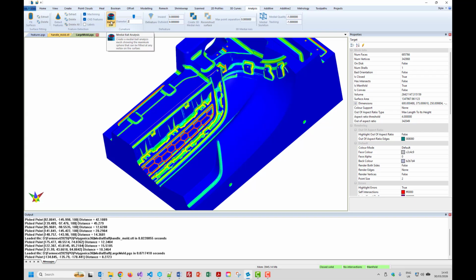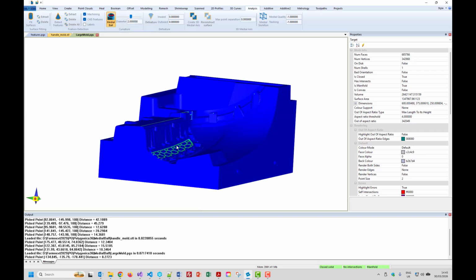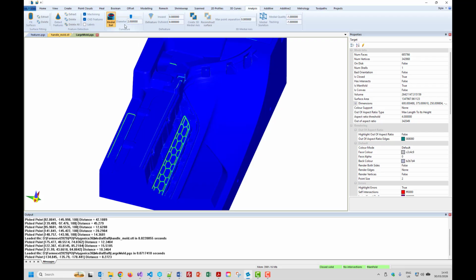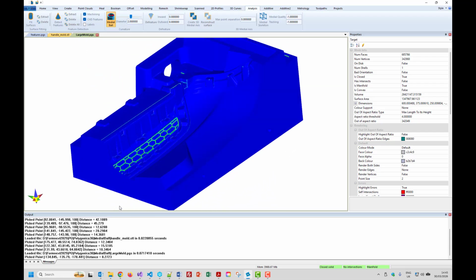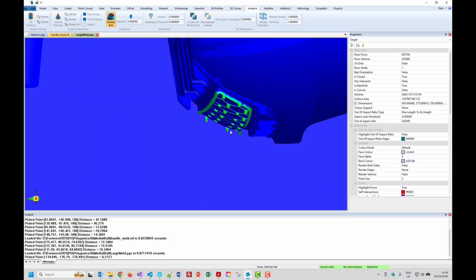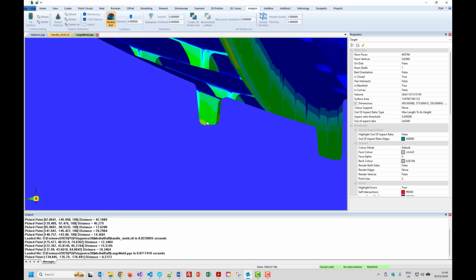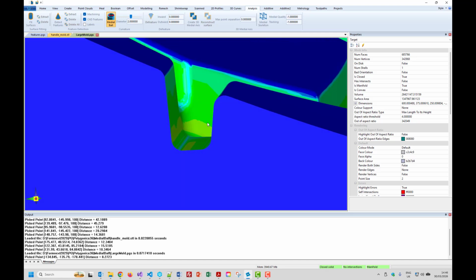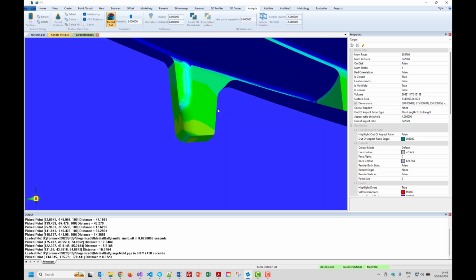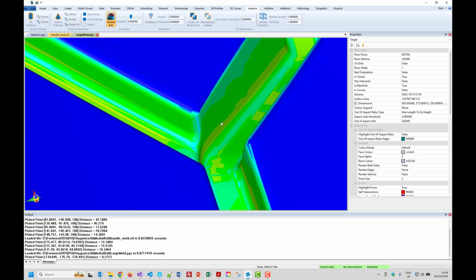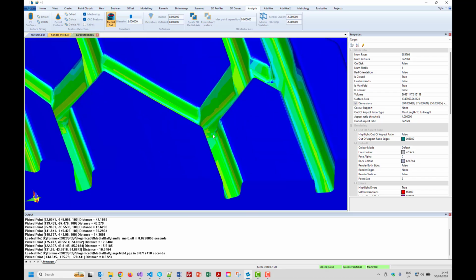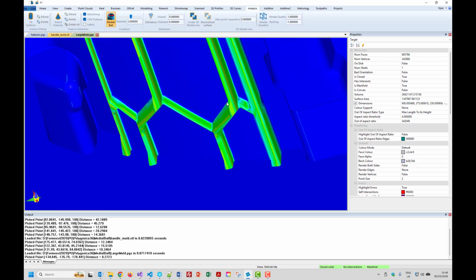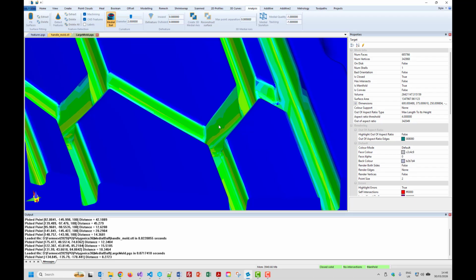And let's go back down. I'm just going to go down to 2 and look at these red regions. So unsurprisingly, with a 2mm cutter, you can machine most of it. But there's these channels at the bottom, and if we look at them, you can see that they're sloped. Maybe they're pointing directly upwards, a bit hard, but the walls are not. The walls are diverging slightly. So what we're not saying is you can necessarily access a tool in there, but what we are saying is that if you were to get your tool into that, it would need to be much smaller than 2 millimeters.